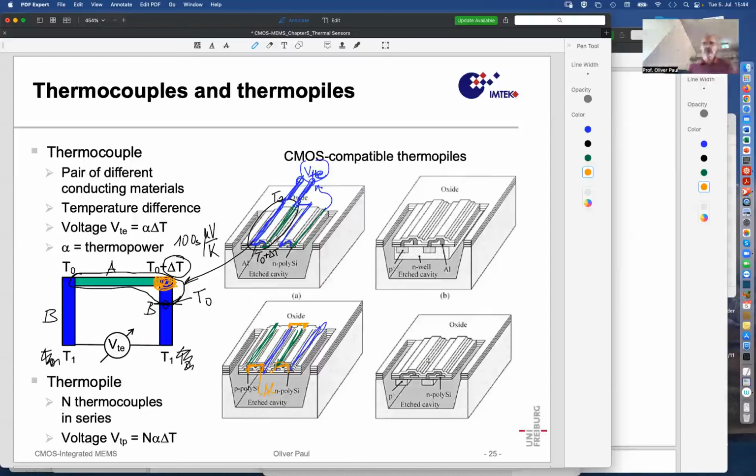Yeah? So then under some external radiation, this delta T can really be produced. If the silicon was still there, that heat would be eliminated very efficiently into the substrate. You wouldn't get any delta T. By insulating the structure, the heat absorbed needs to flow along the structure. There's a large thermal resistance, and therefore there can be large delta T.